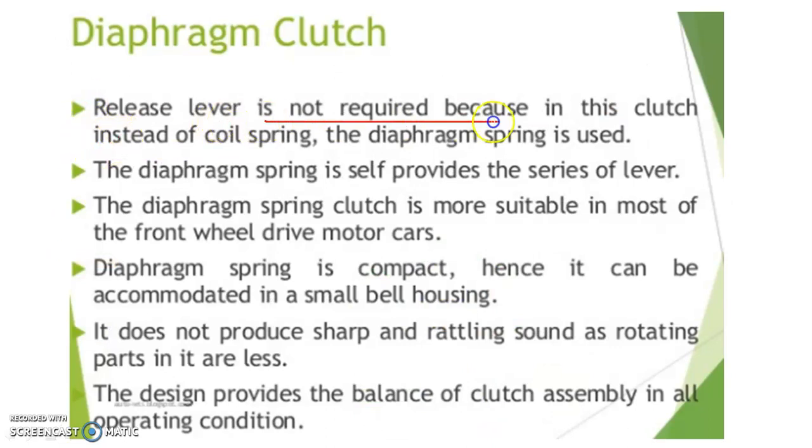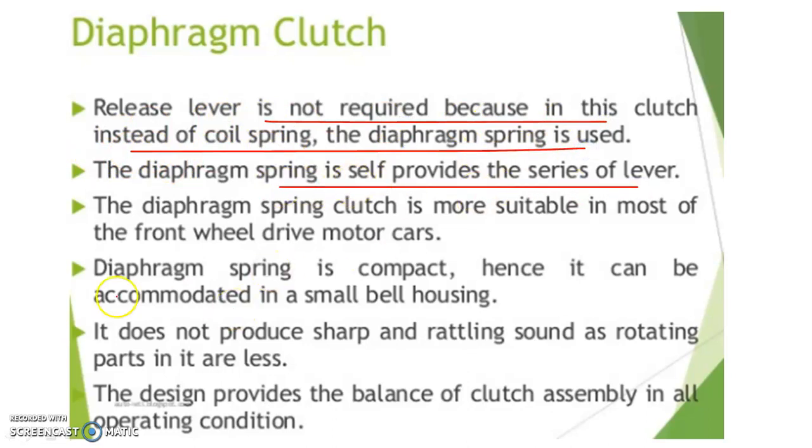Release lever is not required because in this clutch, instead of coil springs, the diaphragm spring is used. The diaphragm spring provides a series of levers. So these are some of the points you can watch here.